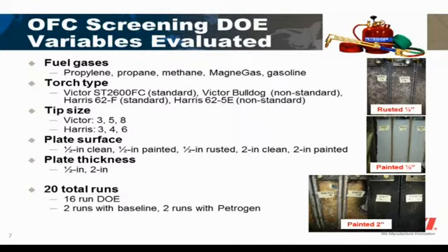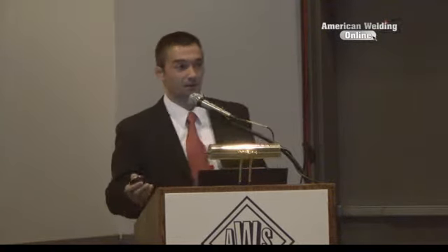So that was pretty significantly different than what our half-inch painted was, which was a little bit too thin in comparison to what was in the shipyard. It was about 0.02 of an inch thick paint. So one of the findings was that for the 2-inch thick painted plates, the special hull treatment tile was a lot thicker, so it was a dominating factor in the DOE. But we also got good information out of it, and we were able to identify what was significant and what wasn't.